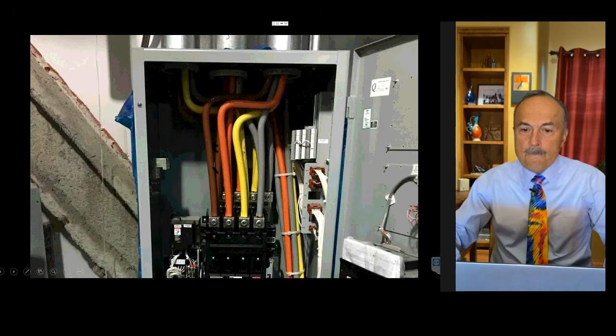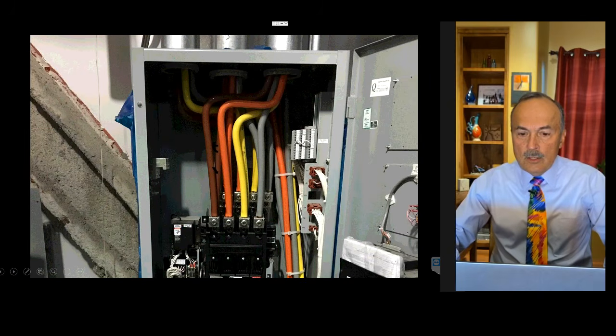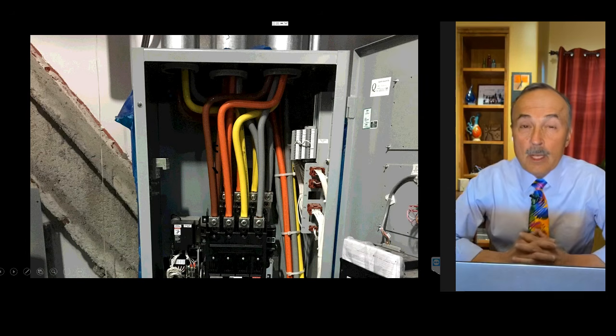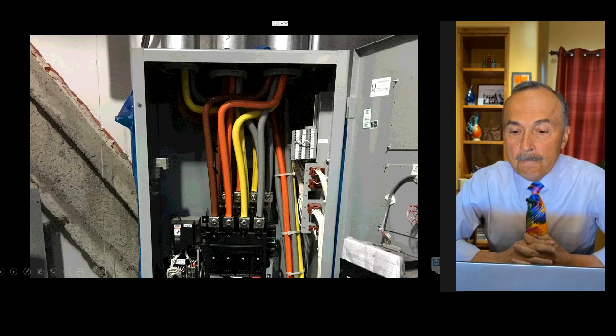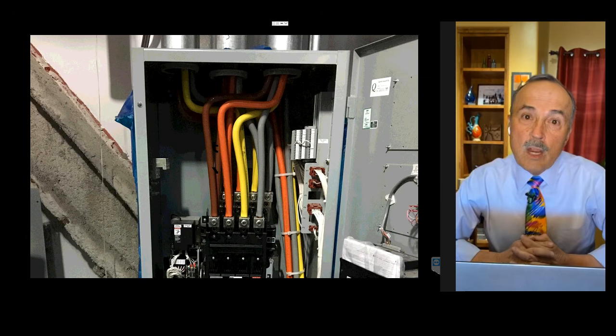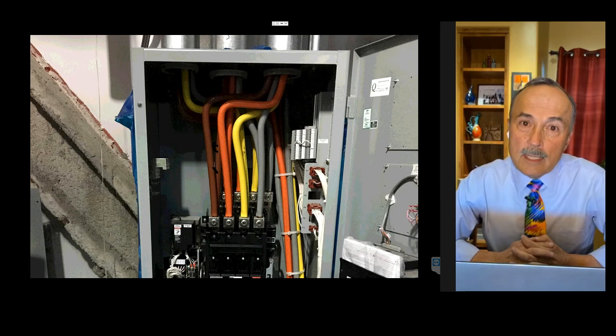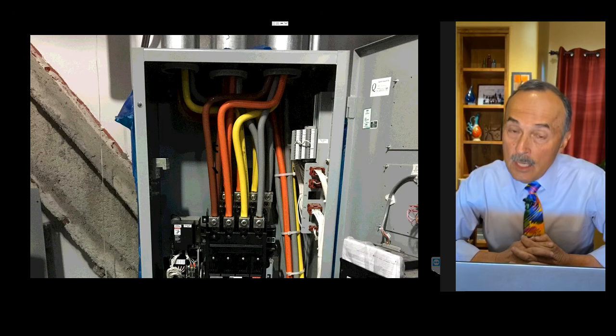Take a look at this one. This was an installation in New York City, and the engineer on the project said, you can't do that. I want you to take all of the wires that you bent and replace all the wire, because that wire is defective, because there is a requirement of a minimum bending radius. Well, there is no requirement of a minimum bending radius of a conductor in the National Electrical Code.